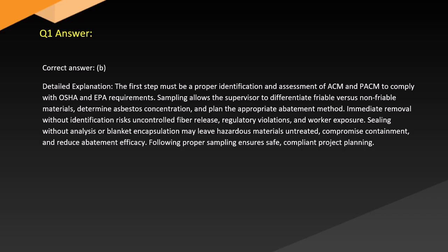Immediate removal without identification risks uncontrolled fiber release, regulatory violations, and worker exposure. Sealing without analysis or blanket encapsulation may leave hazardous materials untreated, compromise containment, and reduce abatement efficacy. Following proper sampling ensures safe, compliant project planning.